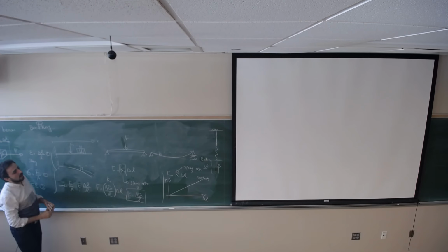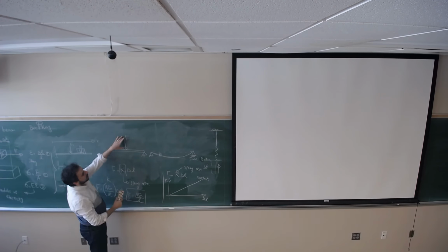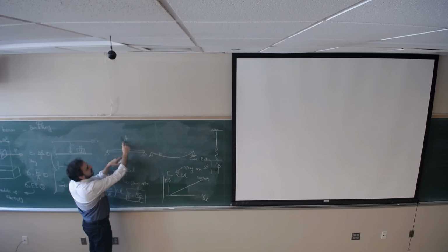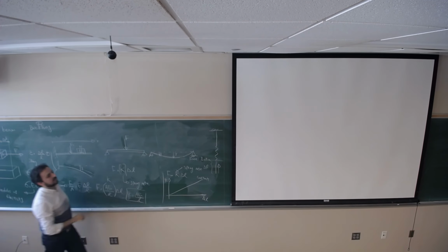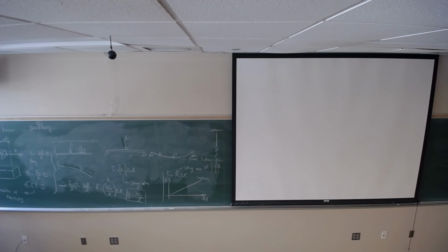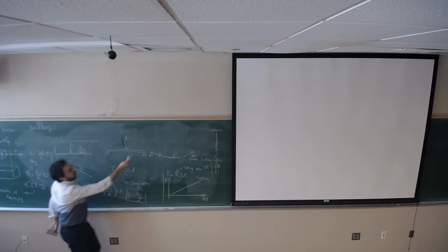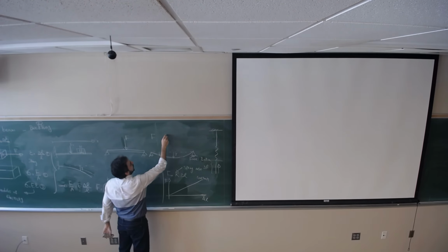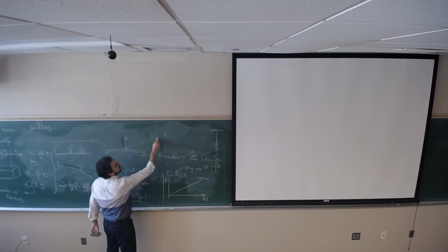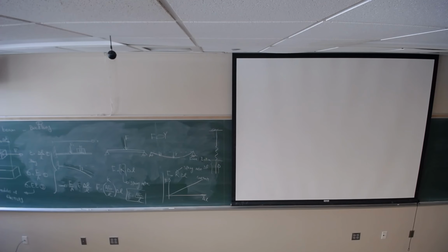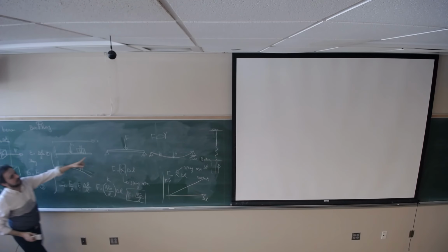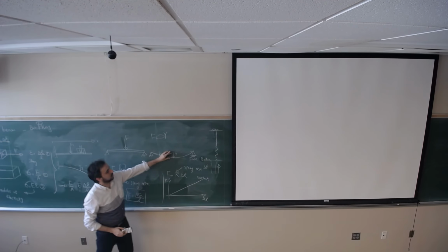Now, if you can find the correlation between this F and the deflection at the middle of the beam, F and y, then whatever is connecting these two is called the spring rate for the beam, which is under a loading that makes the deflection.